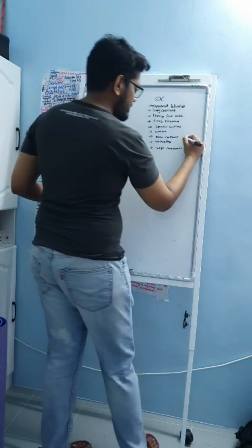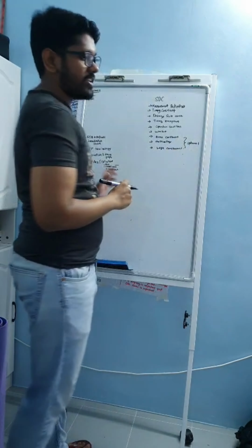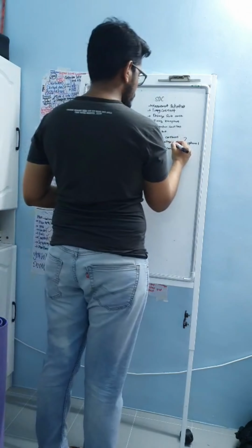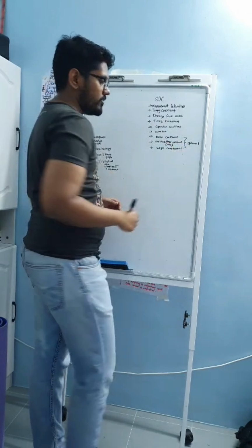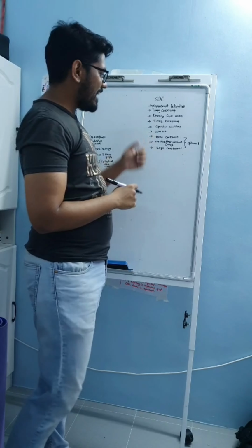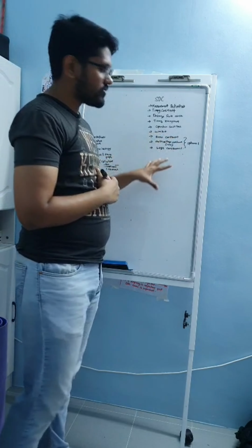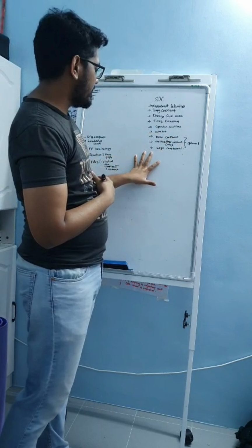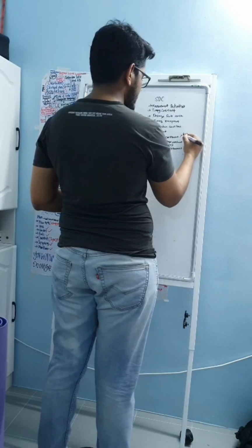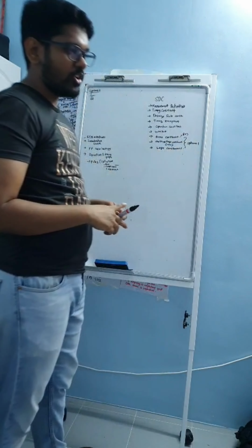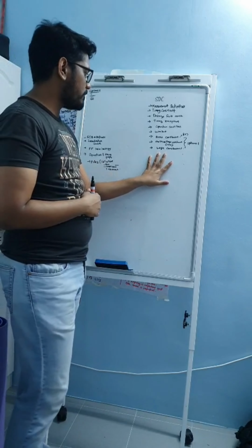I think this is actually optional. It depends. Normally, whenever you have a multi-voltage constraint, it is defined in your UPF itself. And then the area constraint, if not much is being added over here, you can do it in floor plan itself. So this is more into floor plan. But for logic constraint, you just want to make sure that you don't insert any small cell. So that's the reason we have this logic constraint.